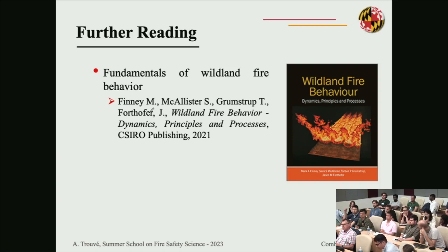So in any fire models, whether you use FDS, FireFoam, OpenFOAM, or any tools that I'm aware of, you're going to have a radiation model that typically is pretty sophisticated. I think that's always been a strength of the fire science community, to pay attention to radiation, which is so important for us, and come up with good model descriptions and good analysis. So you have a solver for what we call the radiative transfer equation, that describes the transport of radiation due to electromagnetic waves in space.